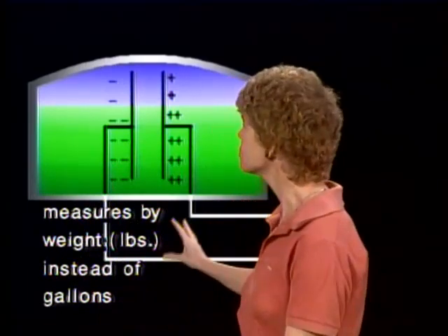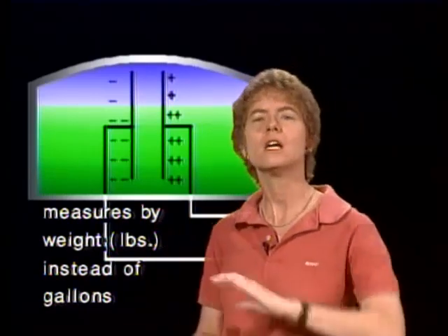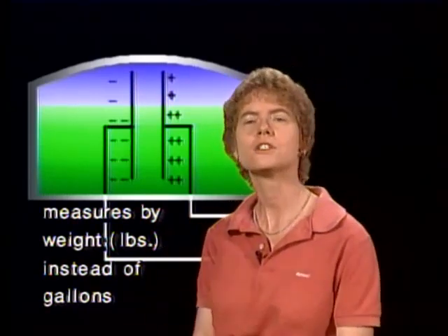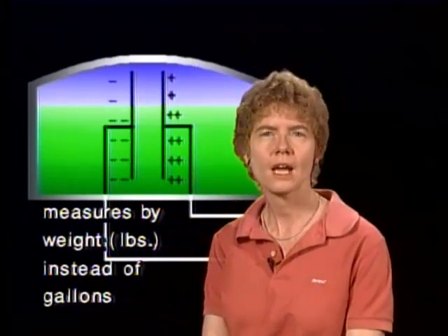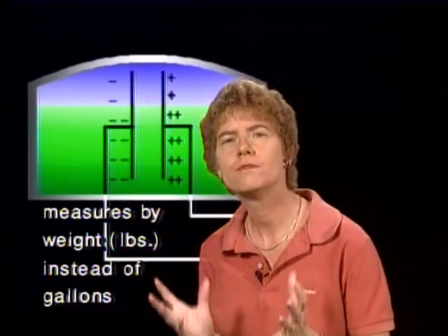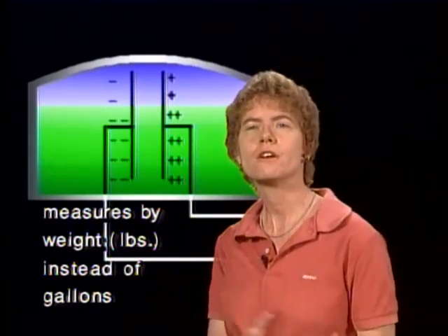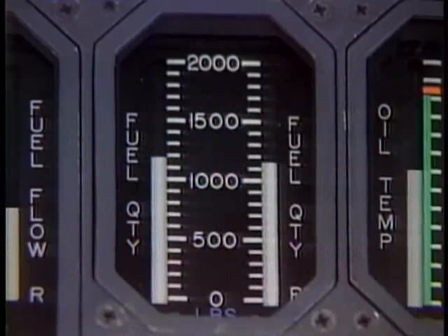And when it measures by pounds like that, instead of measuring in gallons, the measurement will be more accurate because the volume of the fuel varies with the temperature change. So fuel quantity measured in pounds instead of gallons is more accurate. You've always got the same number of pounds, but the gallons of fuel will change depending on what the temperature of the fuel is.